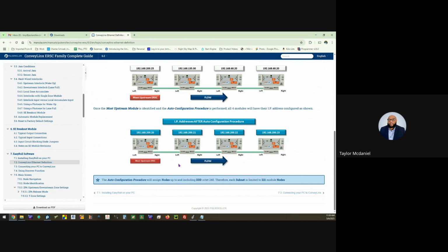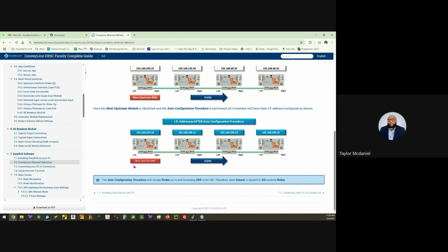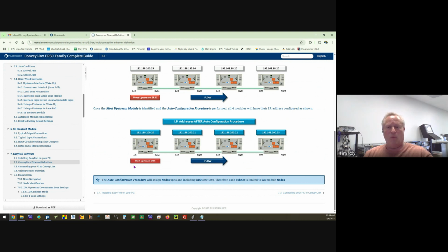If I had 128 cards on that network for that EN2T, God forbid if I do, what is the RPI? I know I talked to tech support and they talked about RPIs kind of cascading. Yeah, so it kind of depends. If you do have a full Ethernet card, let's say you did put 128 on there, depending on what they're doing, you could have higher or lower RPI rates.